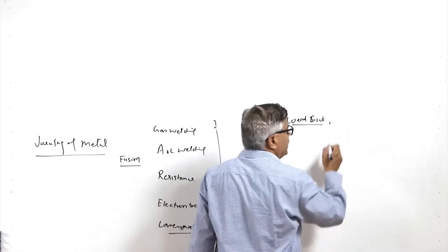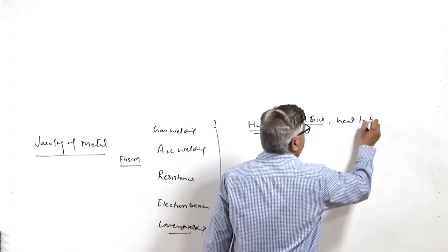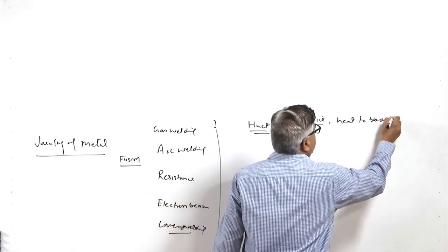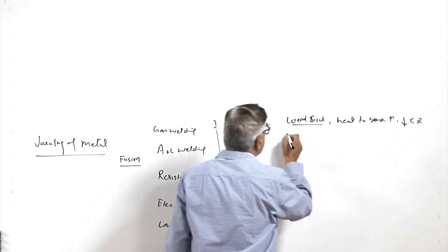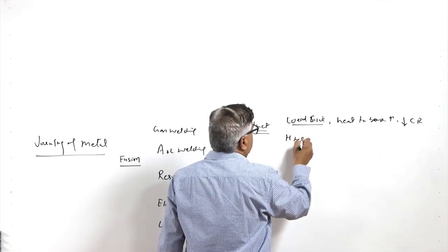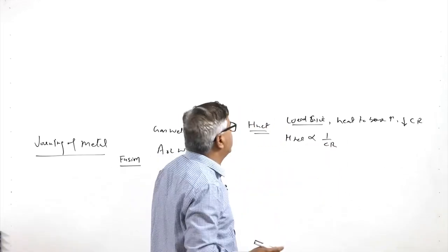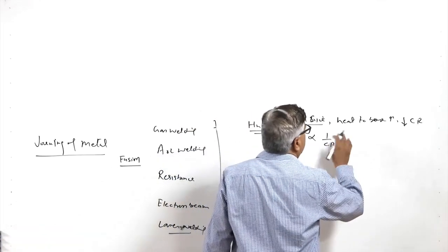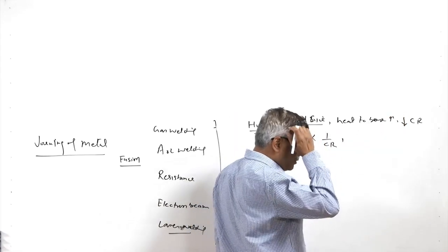The amount of heat delivered to the base metal also increases, which in turn reduces the cooling rate. In general, heat input is inversely proportional to the cooling rate experienced by the weld metal, because of the greater amount of heat being supplied to the base metal below the fusion boundary.